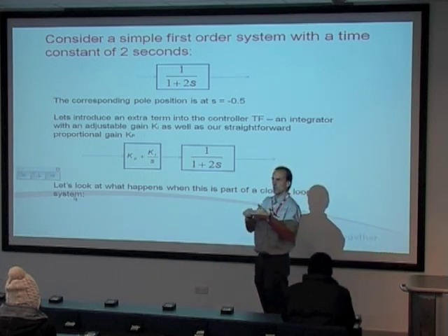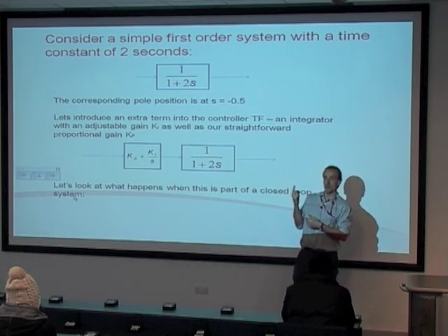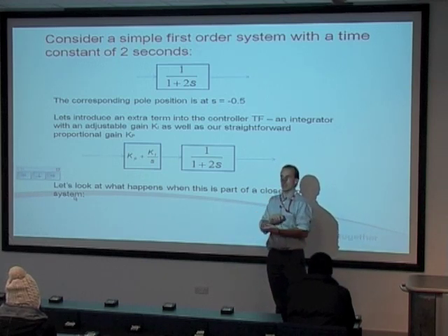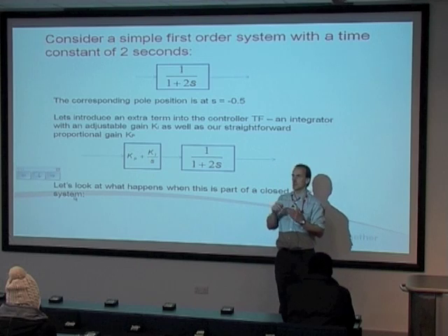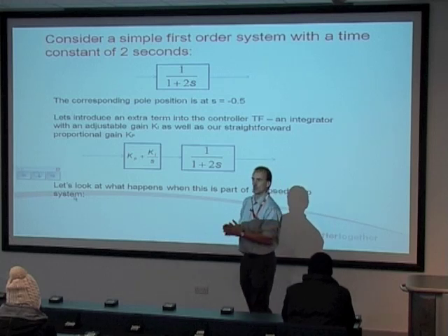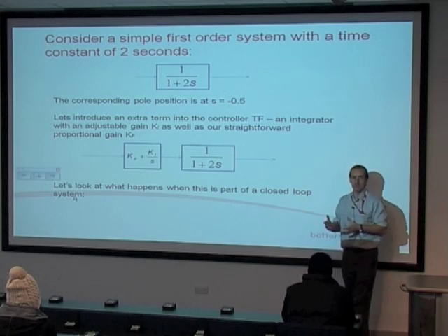And that error signal, if I just let it through without a gain, I've got 1 mile an hour's worth of push to open the throttle. If I put a gain in there, let's say times 10, I've got 10 times as much controlling effort to open the throttle. In other words, I open the throttle more quickly. So the response to the whole system speeds up.